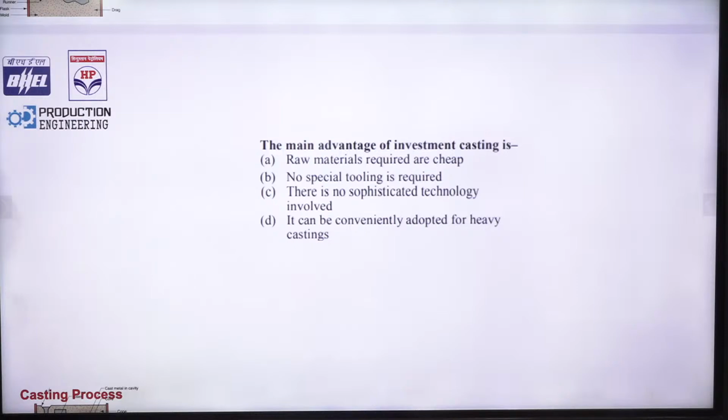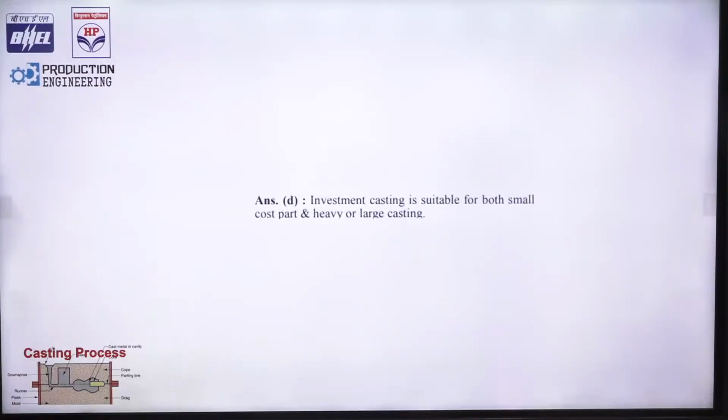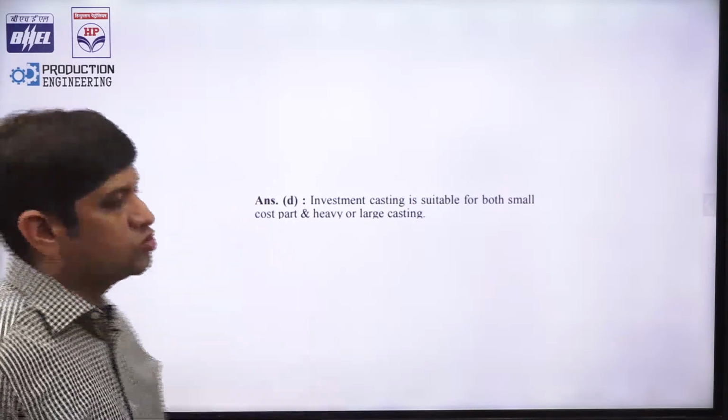Okay. Heavy castings. Can it be used for heavy casting? Yes. Small, heavy and large casting. Investment casting can be used for small parts. The surface quality is very good, and nowhere do we get to know that it cannot be used for large size. Yes, it can be used for heavy size.